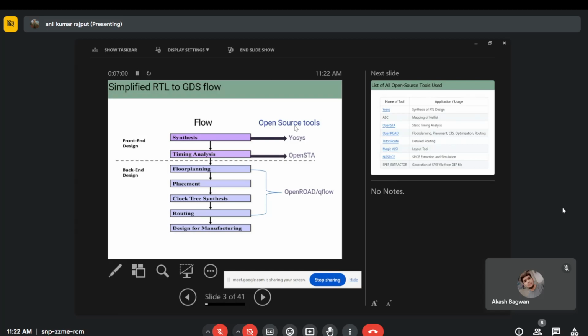After that, routing. Routing is how the power supply, ground supply, and the signal are routed to the cells from the outermost part of the IC. For that, we perform the routing. After the routing, we get one file called a GDS file. GDS stands for geometric data stream. It defines the geometry of your IC and its layout inside that IC. That is basically called the GDS. That GDS is supplied to the technology foundry or any vendor who will fabricate your IC.